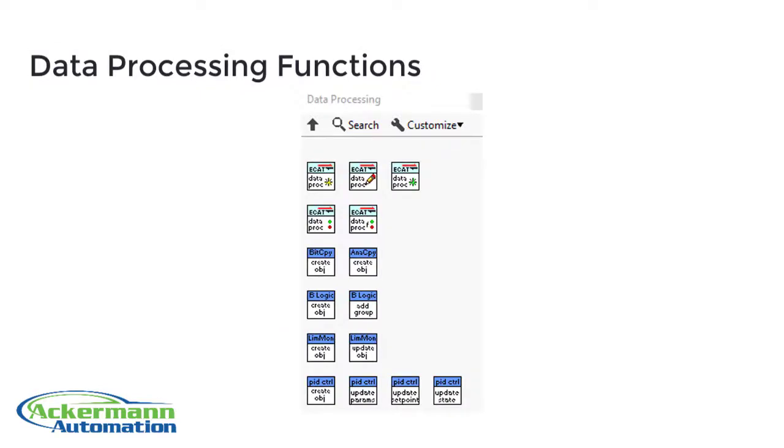The EtherCAT library for LabVIEW comes with a set of predefined functions to work on the process data and the master cycle. These functions are executed in each master cycle in the real-time system. In our application we are running the master cycle with 1 kHz. So the PID controller is executed deterministically each millisecond.